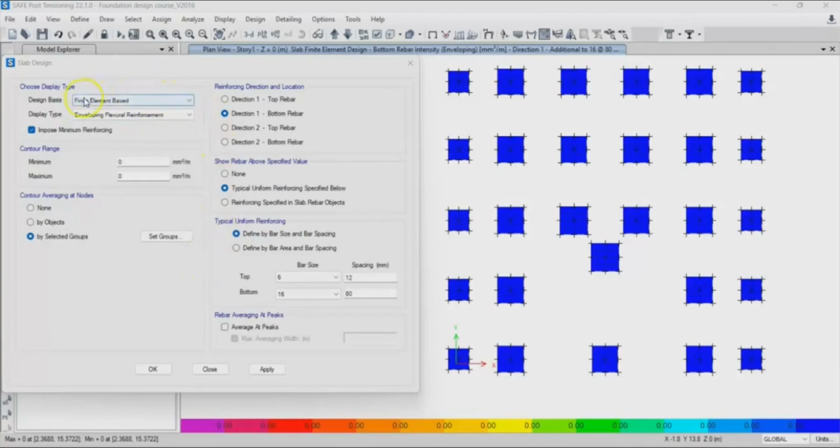Now that we understand the finite element-based method and the history-based method for designing the isolated footing, now let's see if we can also provide mat foundation for this footing. Okay, so we know that when you're providing mat foundation for your footing, it means your soil is very weak, right? The safe bearing capacity of your soil is weak, and in order for the soil to be able to properly transfer the load into more area, you have to provide a mat or raft foundation.